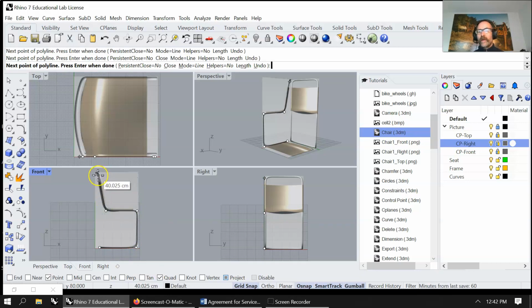And it is critical now at this point. Most people know that they can go over to the right and snap across here. And if you want to make it ortho, hit shift because you've got it on your object snap. I'm not even going to do that. But the main thing is right here. Look up at your perspective window. How am I going to get this point out here, away from here, without snapping to all these other areas?